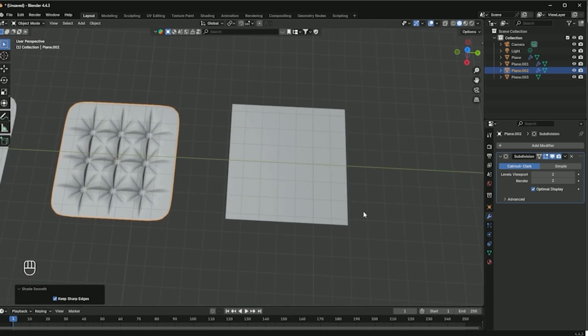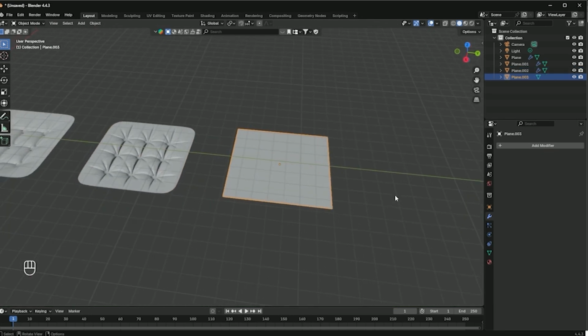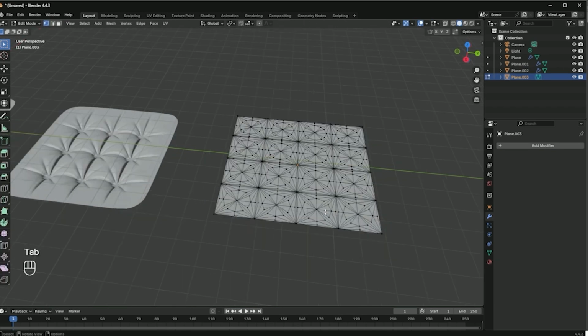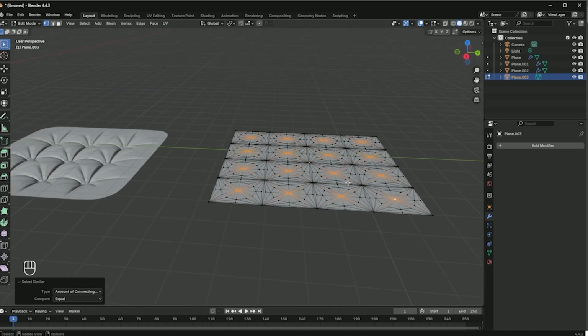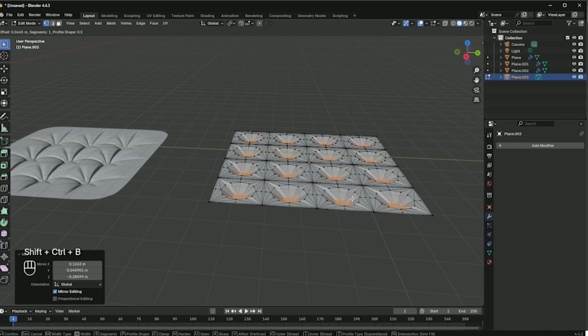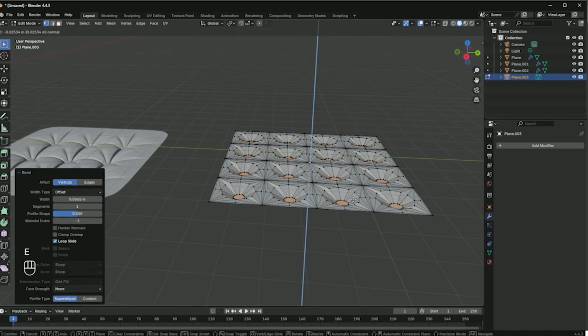Alright then, I will go ahead and select this object, press the Tab key on my keyboard, and slowly transition back into edit mode to continue. If you remember, in this part, I came and selected this area. Now I come here and select this area again, press Shift+G, and from the similar menu, I choose Edge to select these. With the G key, I move it down, then I press Ctrl+Shift+B to apply a bevel to it. I simply press the E key on my keyboard to extrude this section further downwards.